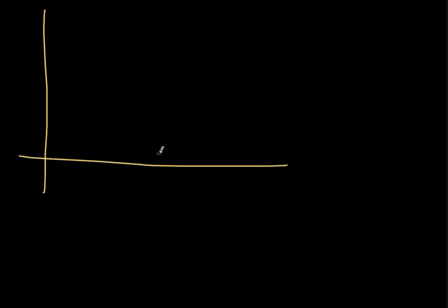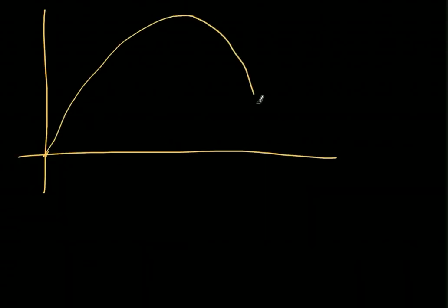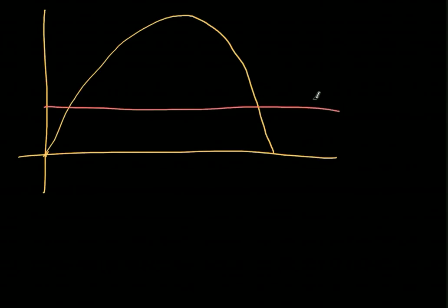So let's take a fresh sheet. The problem is like this. This is PM and this is PE, and currently I'm operating at delta naught at time t equal to 0, and then there is a fault, and then the fault is cleared, and somewhere here is delta C. So this is the critical clearing angle. As you know, this is the angle delta, and up to here it is pi.